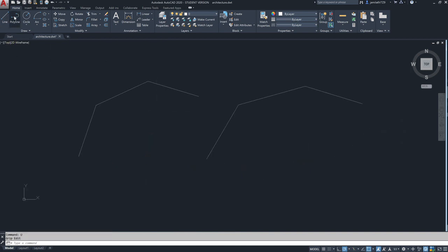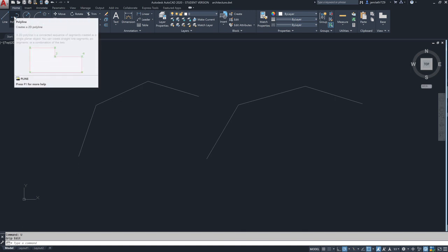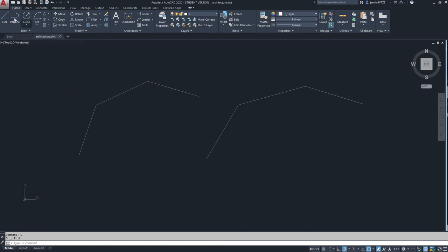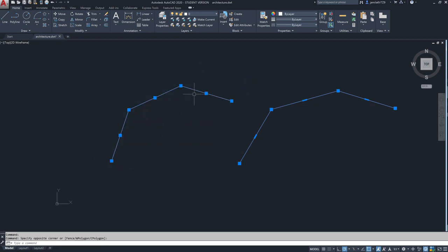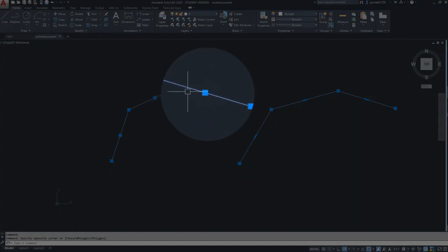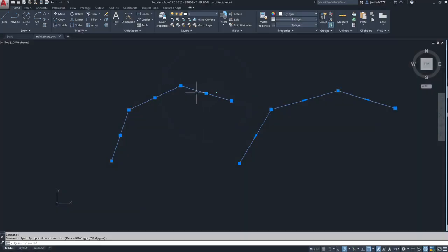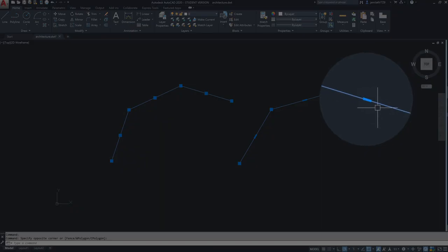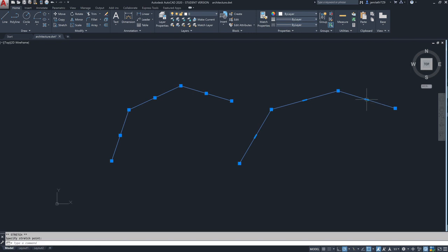We just read this passage from the AutoCAD help, which says you can create a combination of arc and line. So if I select this polyline and I select this line, you'll notice a difference in the vertex. In the middle vertex, you see it's just a rectangle, but this one is a bit different. If I click on that and click again, I get to see 3 options: Stretch, which will allow it to stretch like we just saw, Add Vertex, or Convert to Arc.